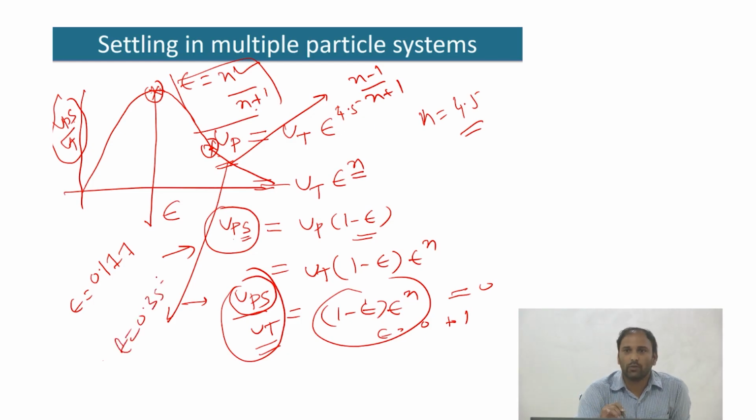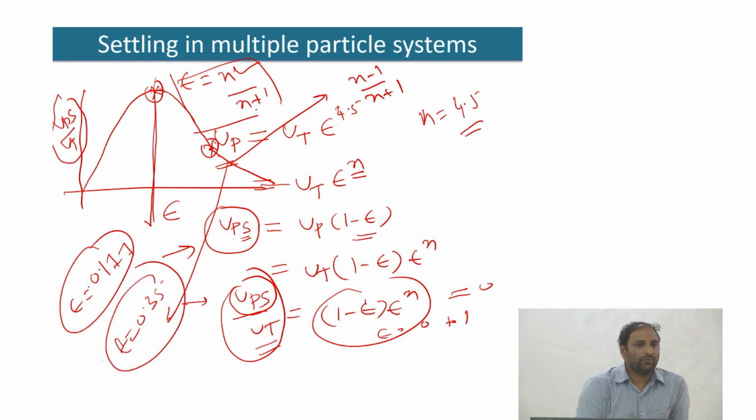The reason why I want to do this is because the type of settling that we talked about, whether sedimentation type 1 or type 2, depends on your initial concentration in the dispersion. Therefore, these numbers define some kind of limits where people are going to see a very different kind of settling behavior depending upon the initial concentration that you have in the dispersion.